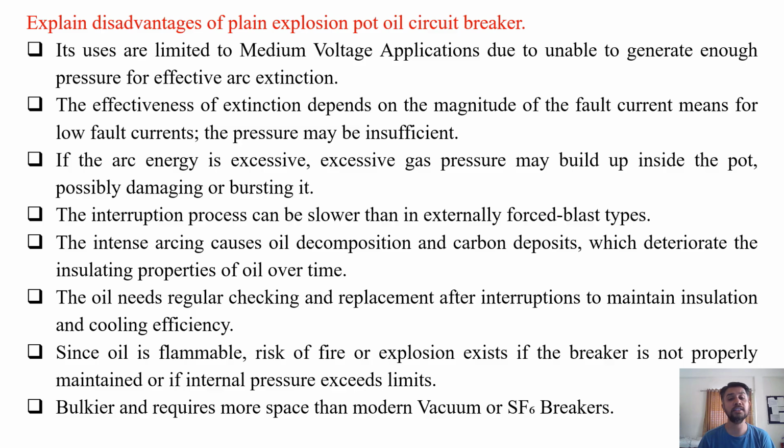If the arc energy is excessive, gas pressure may build up inside the pot, possibly damaging it or bursting it. The interruption process can be slower than in externally forced blast types of oil circuit breakers. The intense arcing causes oil decomposition and carbon deposits, which deteriorate the insulating properties of the oil over time.